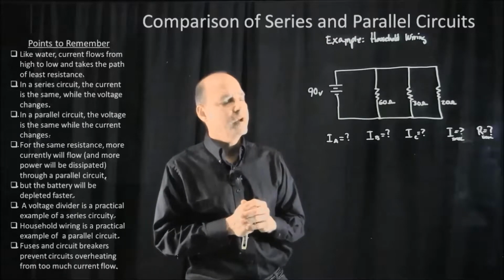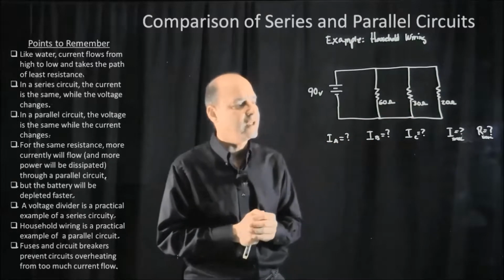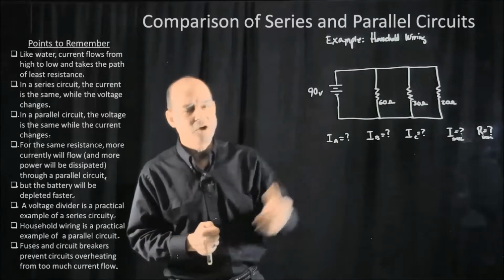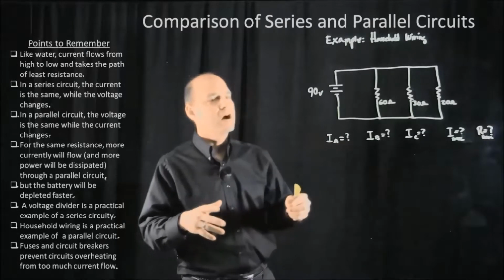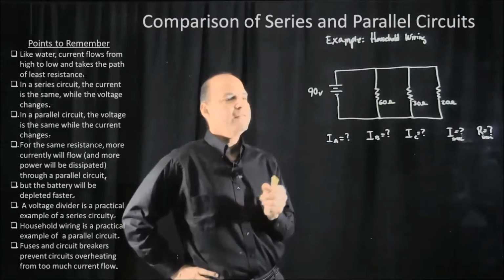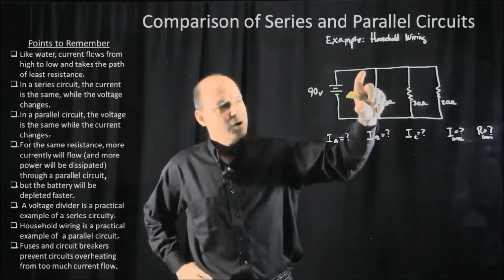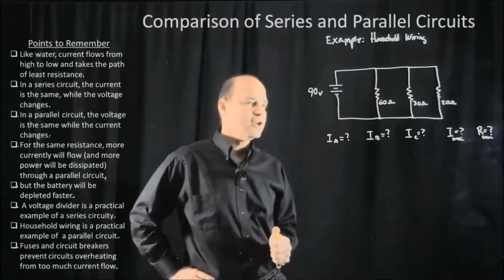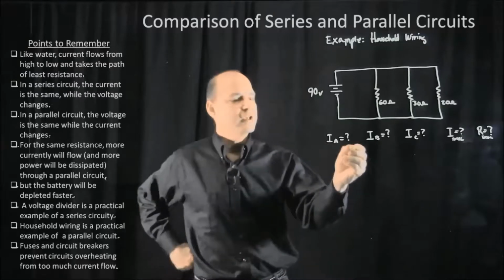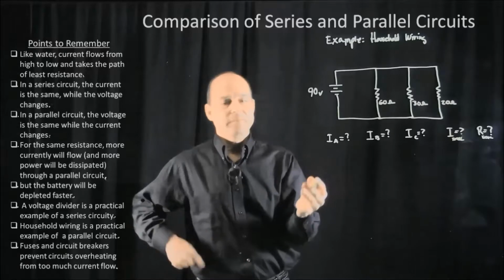In this problem, we are asked to find out what the current through each branch of the parallel circuit is. Wow, that seems like a lot of unknowns. It seems like there's more unknown about this problem than we really do. But if we remember that the voltage is the same across every branch in the circuit, then I think that helps us. So finding out what the current is through the A branch of the circuit,